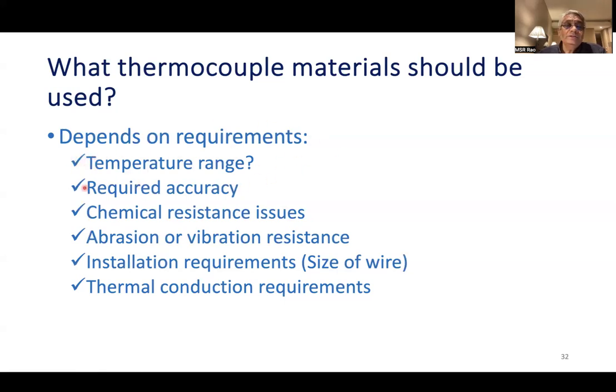So you need different thermocouples depending on the temperature range of measurement, the required accuracy, and you also need to take into consideration the chemical resistance issues, because there are some thermocouples that you cannot expose to a chemical environment during the preparation process. The material itself may be emanating some toxic gases that might affect the performance of the thermocouple.